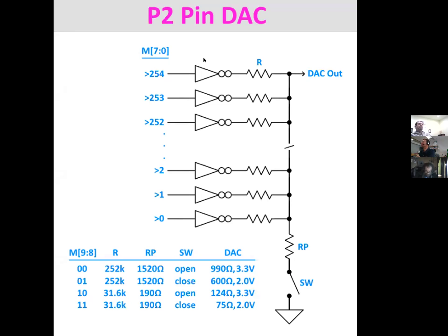And I've just shown the first and last three to keep it simple. But what you have here is a constant impedance DAC, which is really important for pushing high frequency signals. It's simpler maybe to make an R2R DAC, but the trouble is it's going to be very high impedance. So if you want to drive really fast analog loads like video, there's no time for any kind of feedback loop like in an op amp or anything.